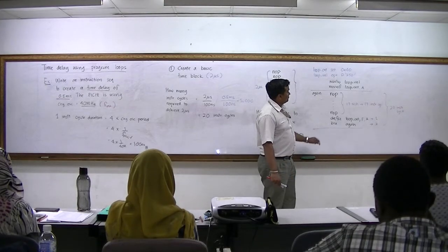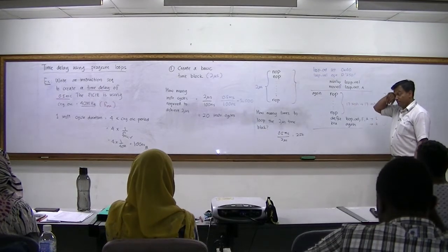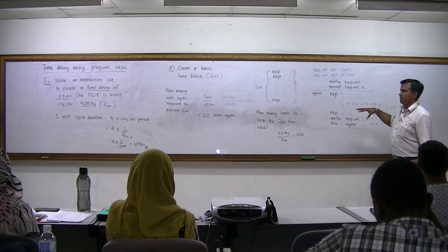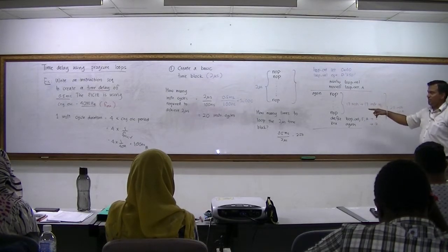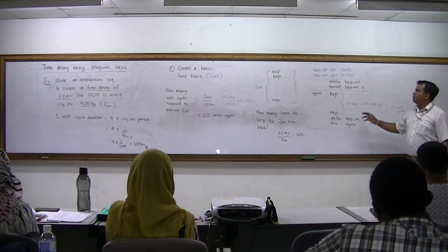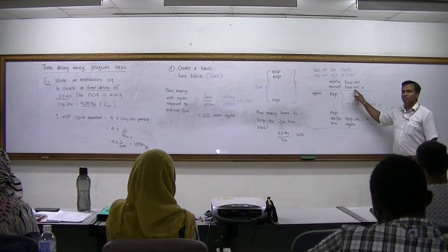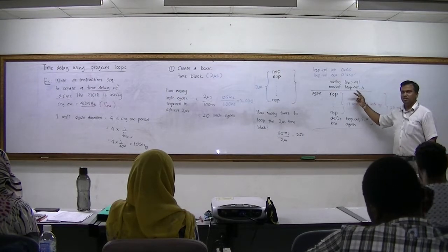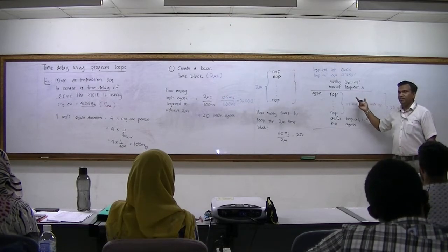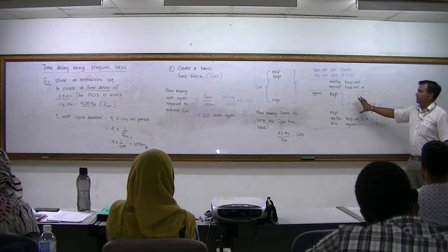This is because there is a way of doing it. I have not come to that part yet. So this is one technique of doing it. We'll come back to that later. Why a bigger number cannot be used is because the loop count can only hold a value of 255 at one time. So if you need to loop more than that particular value, you cannot sustain it. But there is a way of doing that. We will do multiple loops. But before we go into the multiple loops, see this one.